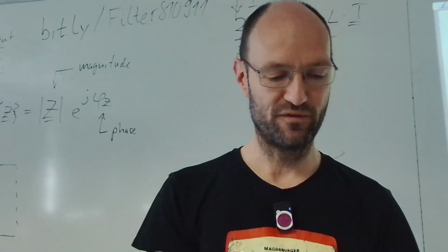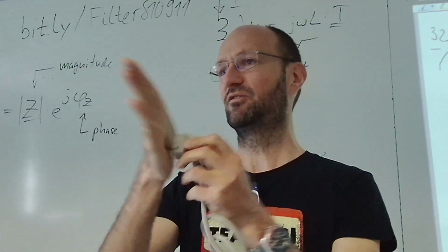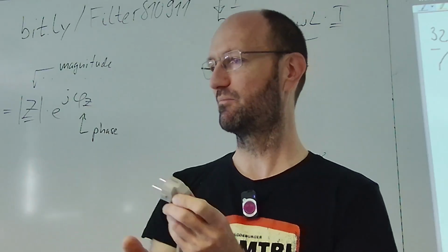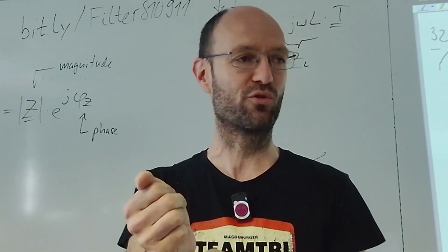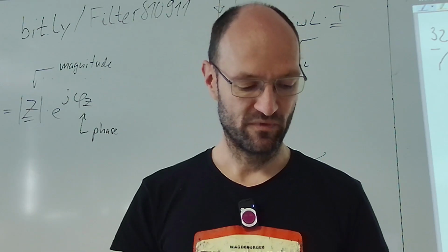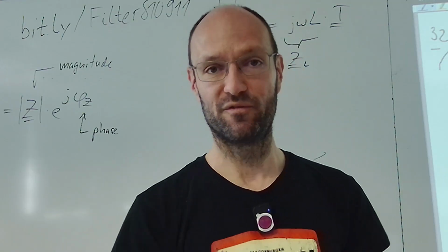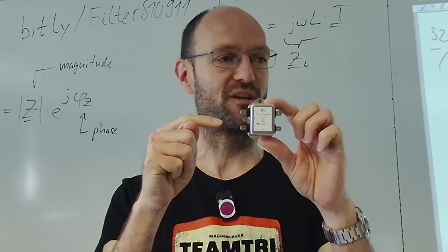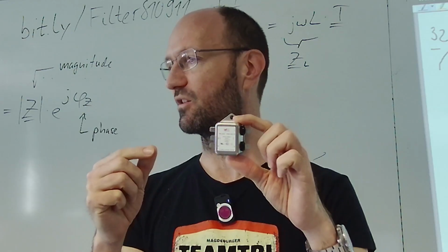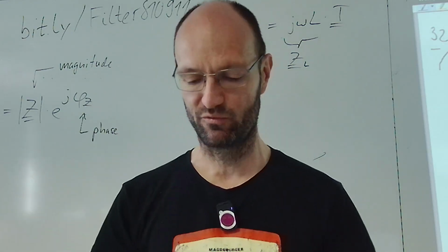And so now if you would take the cable and touch it, you would get some electrical shock due to this voltage. So the purpose of the resistor in parallel to this capacitor is to discharge the capacitor over time. It's a pure discharging resistor.